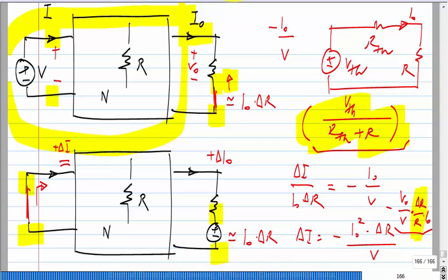If you know that the changes are going to be small over a certain original circuit for which you know the solution, you can use the original solution and some slight approximation like this to find the sensitivity. This is like finding the derivative, right. Derivative, we are told that it is small change divided by small change as the change is going to 0. As the change does become infinitesimal, it becomes exact. Here also it is the same.